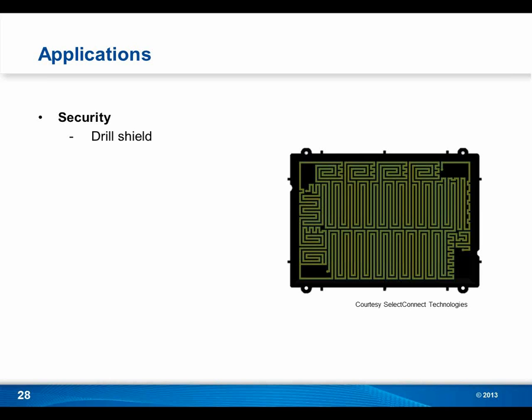So these devices basically are a cover that has a detection circuit on it. Now you see it's a fairly intricate circuit, and most applications in real life actually look a whole lot more intricate than this even. So in order to produce something like this, there's really no other technology that can do this other than laser direct structuring, because we deal with really small, long lines, and you can imagine it's impossible to flow a liquid plastic in a two-shot molding process in such a long channel without the material solidifying before it reaches the end of the line. So again, yields would be impossible with two-shot molding. So again, it's an interesting application where LDS makes the use of MIDs even possible right now.